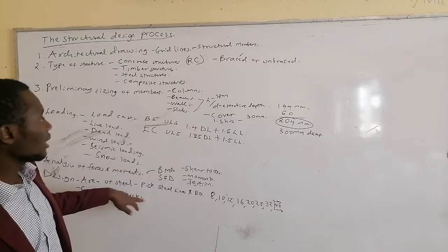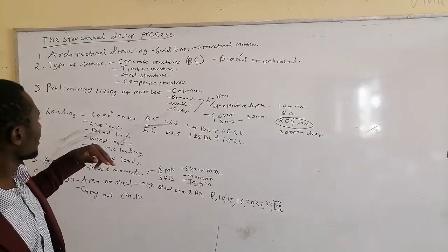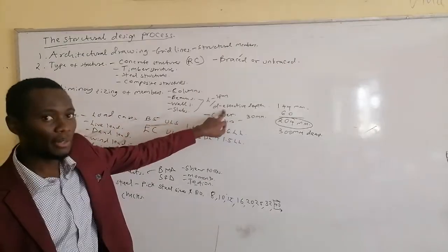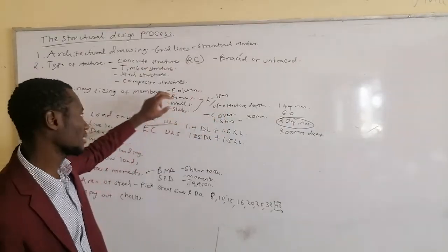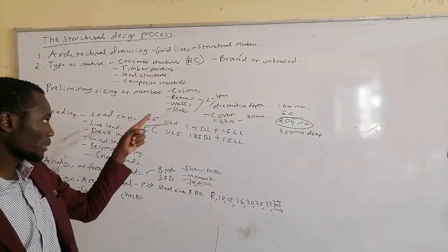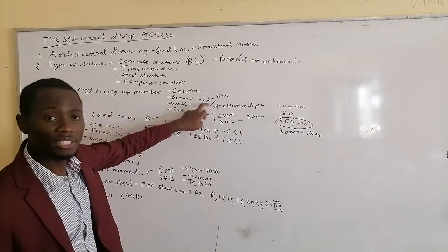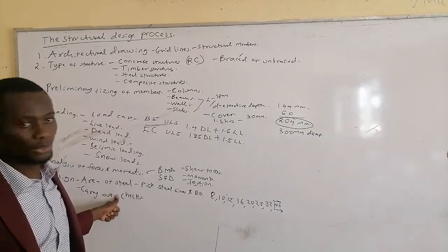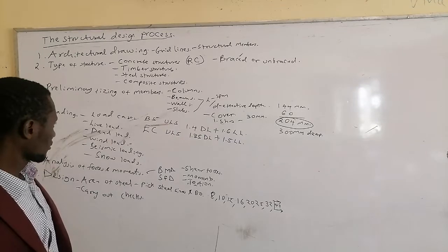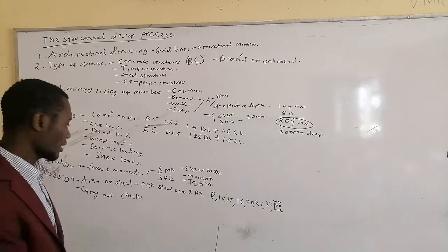And that is where I advised that we use L/D whenever we are preliminary sizing our beams and slabs, because when you pick something that fails there, it is also going to fail when carrying out this check. So we carry out the necessary checks.